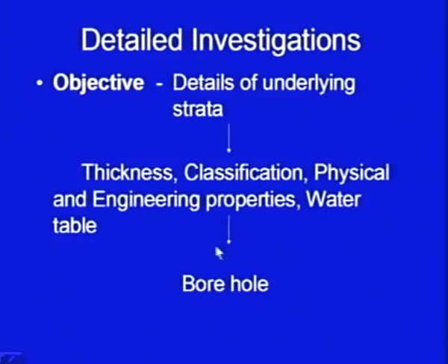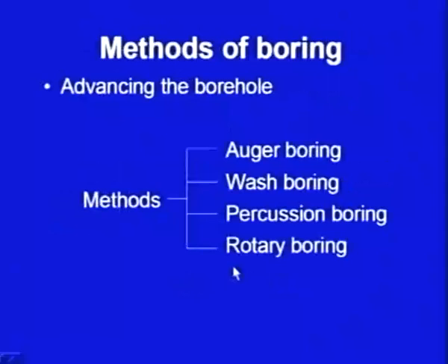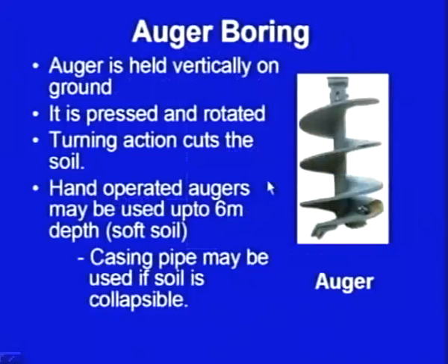The bores are advanced and this investigation is done through boreholes. There are several methods of advancing the boreholes. First method is auger boring, wash boring, then percussion boring and rotary boring. Let me in brief discuss all these methods.